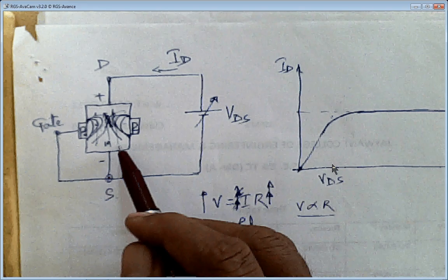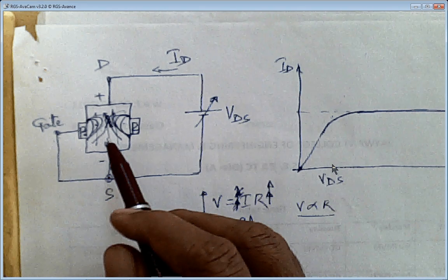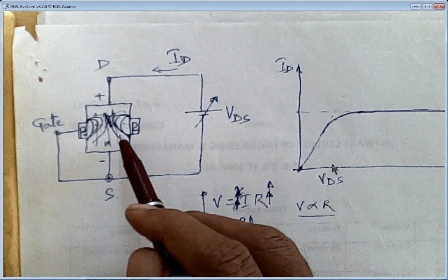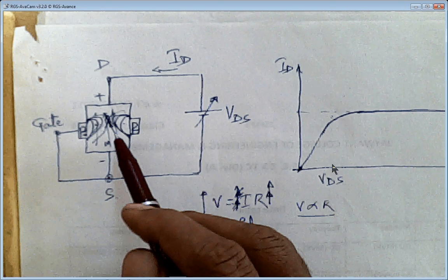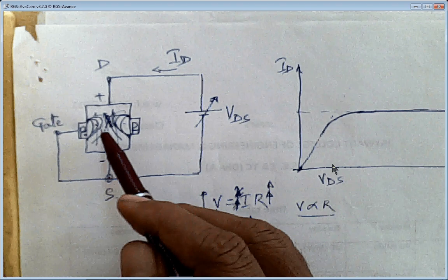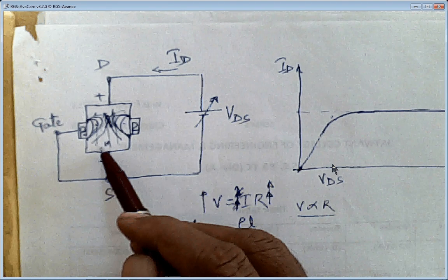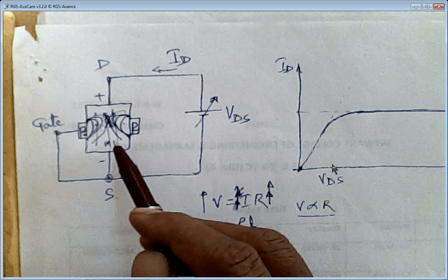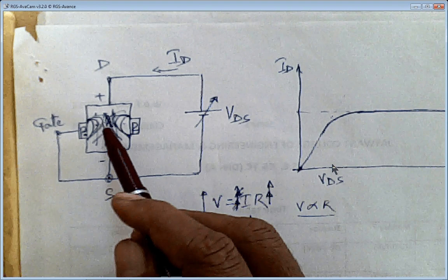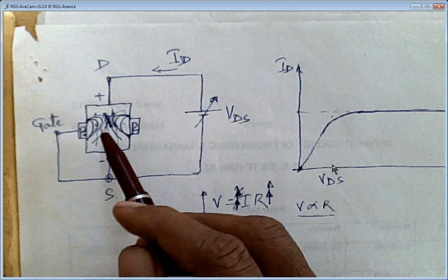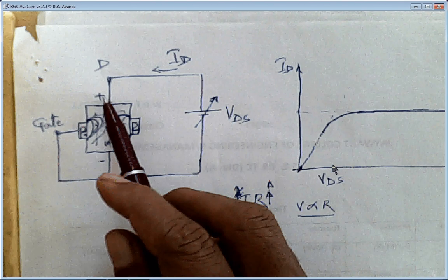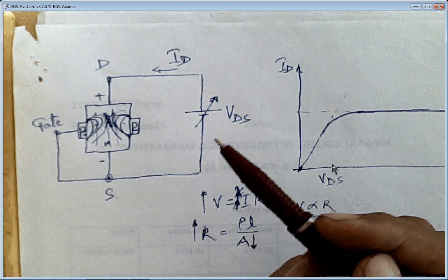These charge carriers were trying to travel from negative to positive, and in between they are obstructed by this depletion layer, which is charge ions, not carriers but ions. And because of these ions, the electrons which have huge kinetic energy will collide with these ions and will release more electrons, and all these increased electrons will now travel towards positive. That means your current has now increased.